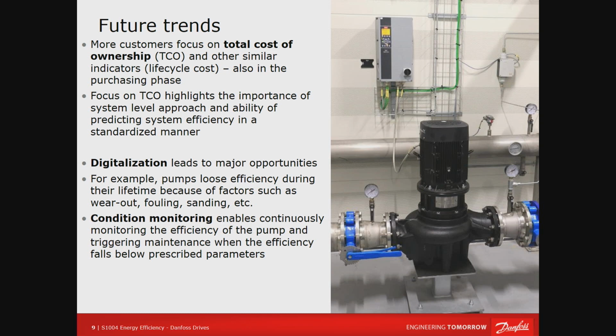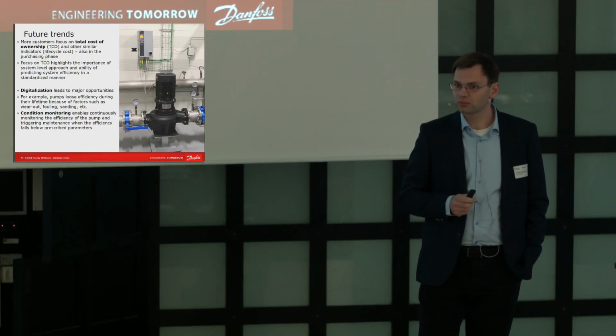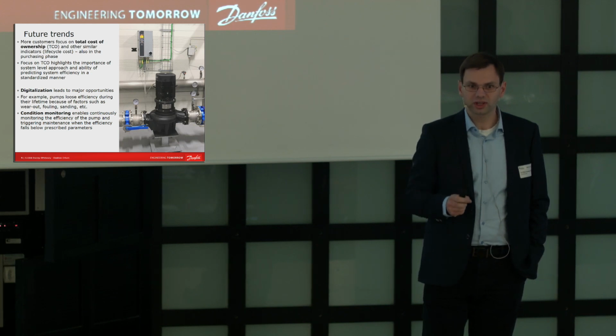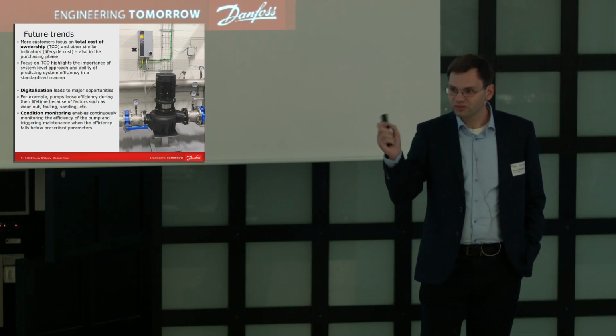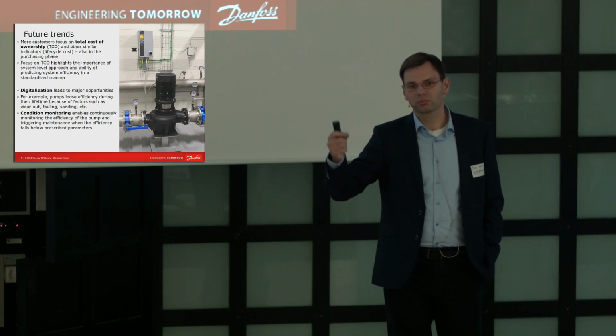If you are able to monitor this with a condition monitoring system, condition monitoring of the pump, then you are able to perform some maintenance to clean the pump before you get so down that you observe, or the maintenance guy sees it without measuring. We have seen this morning also a presentation from a chocolate factory with a fan, where the fan was cleaned when making the upgrade of the system.